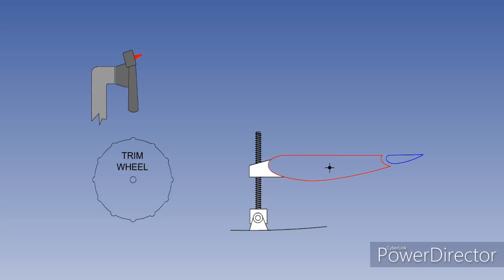You can see that the trim input controls in the cockpit are the same, but now pitch trim is accomplished by changing the incidence of the whole tailplane. As before, for pitch control, an elevator mounted on the trailing edge of the tailplane is still used. For pitch trim, the incidence of the tailplane is changed with the screw jack. The screw jack is mounted inside the rear fuselage and is driven by motors mounted on a gearbox at the base of the screw jack.